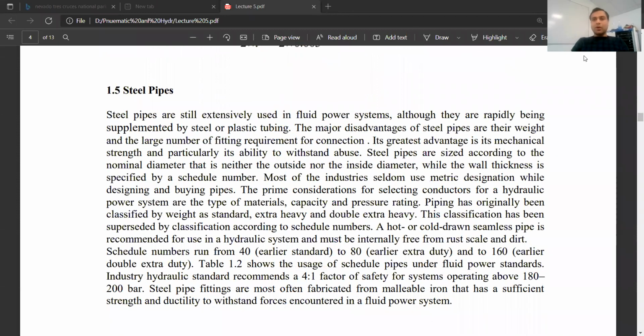The most common type of pipes we actually use are the steel pipes. The reason we use steel pipe is because with the same steel, we can increase and decrease the properties. We can do the heat treatment. We can have corrosion resistant steel pipes. We can have food grade steel. We can have different types of high temperature steels as well. So they have a lot of advantages.